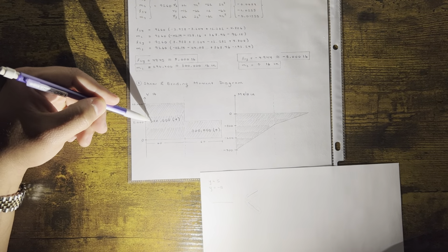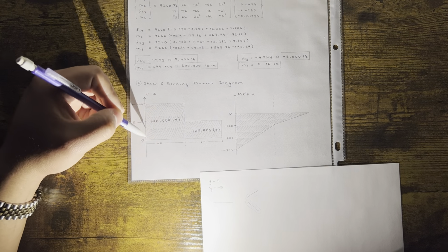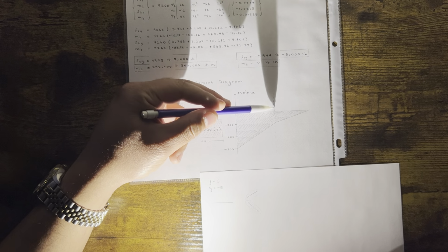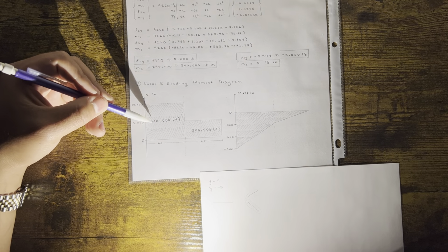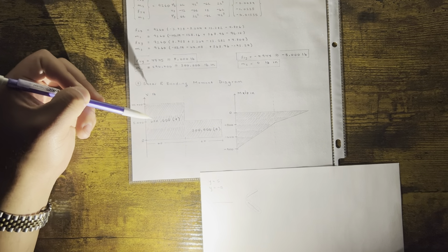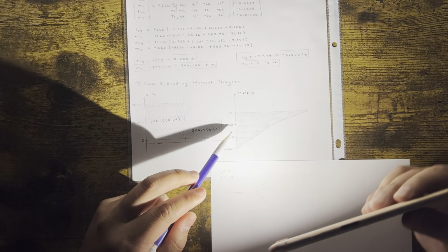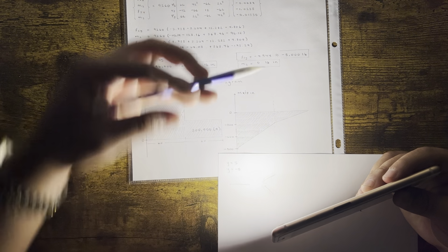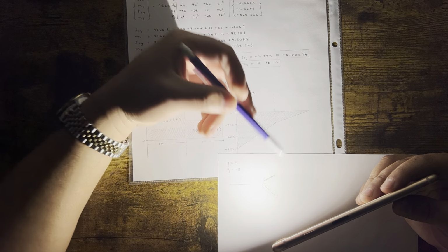So in this case, we go up 600,000. Between 0 and 60, we go up 600,000. So 0 to 60, halfway through the beam, that's what this dashed line is, node 2. Well, we were at -900, but we went up 600. So now we're at -300. This was a positive slope, so we're going up, because of this line right here.